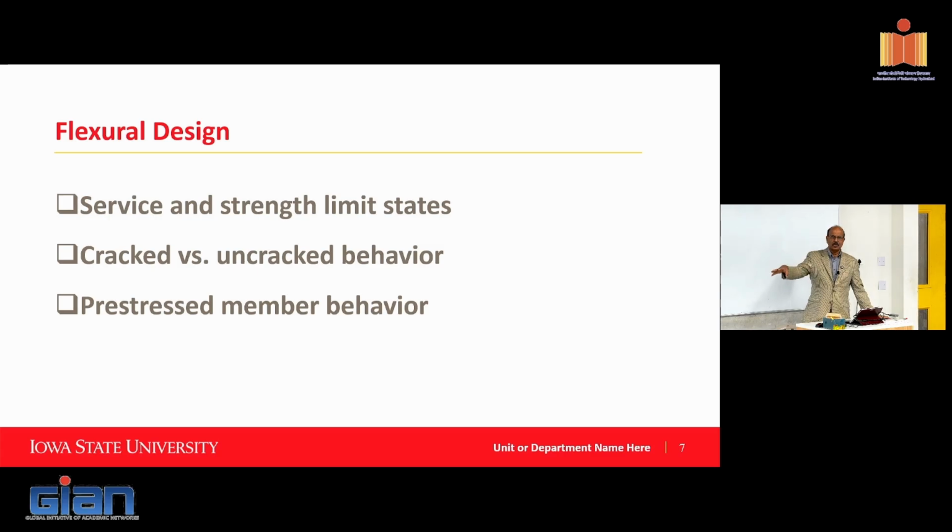And then it has to be stored, and you have to pick the component in the same way when you transport it to the site. And whoever is working on the site, which is a different crew, needs to know they have to pick from four points, not from two points for that particular member. So all of that has to be communicated all the way so that the structure remains crack-free. It's not, again, difficult, but it has to be done.